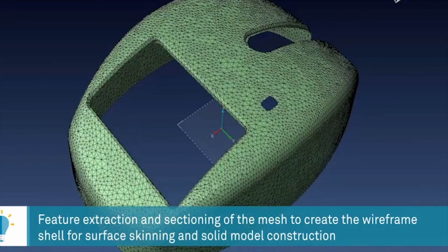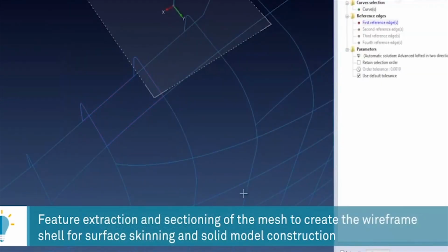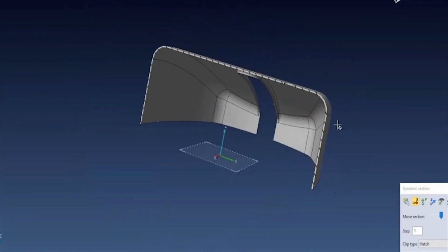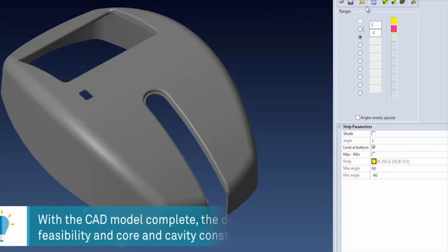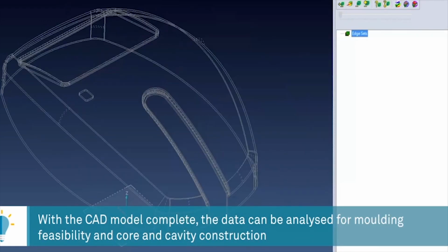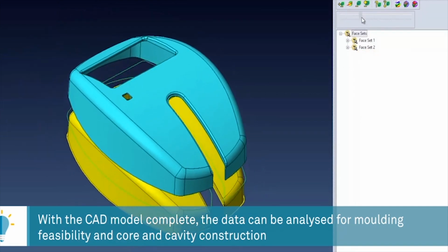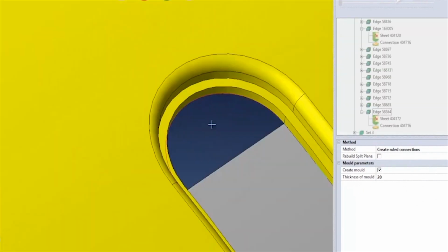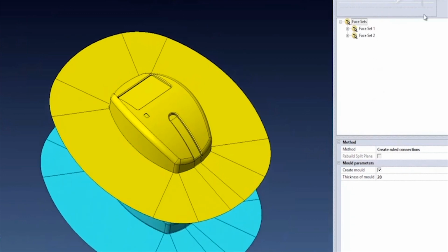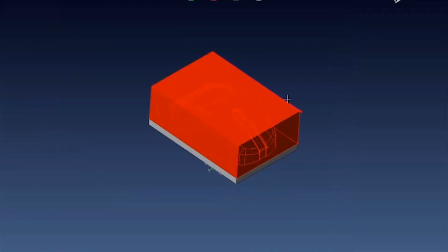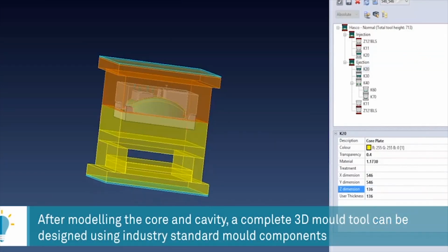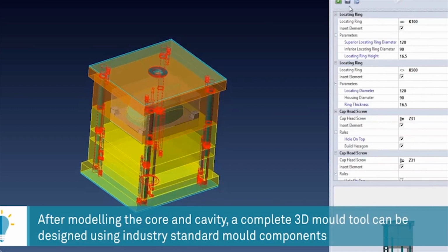For example, if we scanned a broken injection molding tool to produce a new tool, this involves importing the as-designed CAD model and superimposing the scanned point cloud data set of the manufactured part. The RE software allows the user to compare the two data sets, as-designed to as-manufactured. This process is also used for inspecting manufactured parts. Reverse engineering can also be used to scan existing hip joints and to design new artificial hip joints around patient-specific pelvic data. This creates the opportunity for customized artificial joints for each patient.